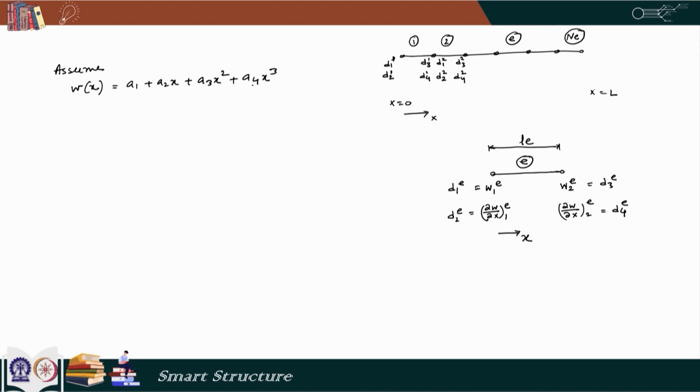So, here I have 4 unknowns and I have the 4 degrees of freedom in the formulation. And the approximation is such that it has at least the second order derivative non-zero, because in the variational form we have seen that the highest order derivative appearing for W is 2. In fact, it has a derivative up to third order also.